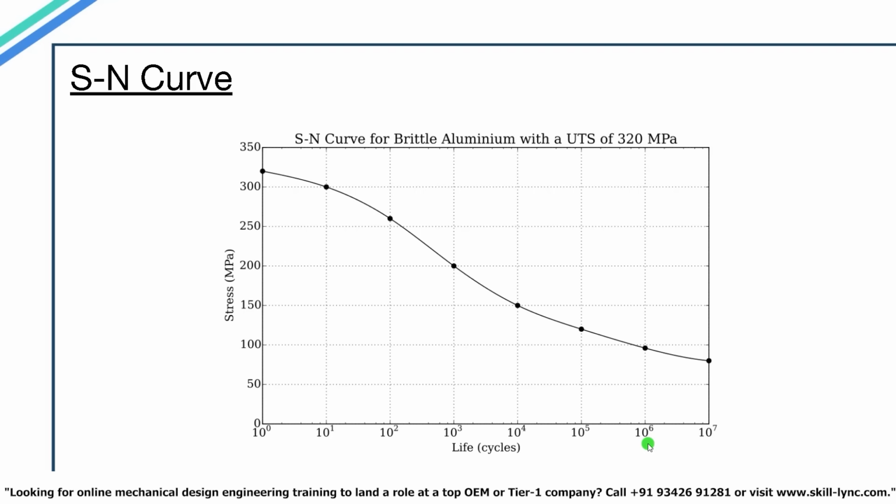So using this curve, it allows us to calculate the number of cycles of load a material can experience before undergoing failure for a given range of stress. Fortunately, we don't need to perform the time-consuming tests ourselves, as the data for these materials is published in many material handbooks and also many code books, and you can actually get the data online.